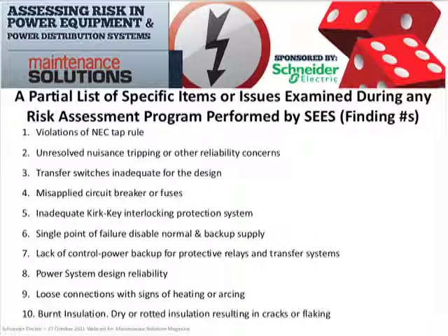The most common type of nuisance tripping of circuit breakers is the ground fault function. The number one reason for having nuisance tripping of a ground fault protected breaker is neutral ground bonds downstream of the breaker. Usually about 70% of the time it's the result of neutral ground bonds downstream.